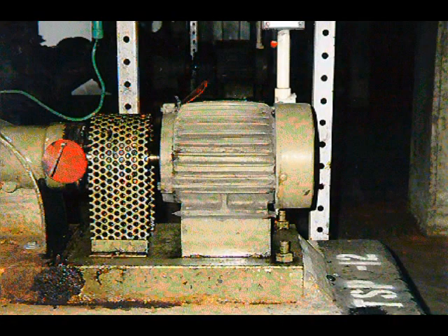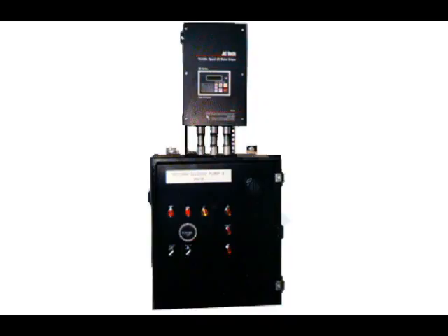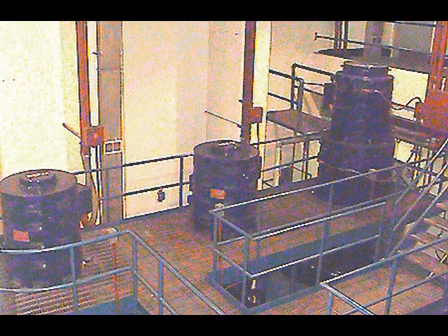There are a number of different types of alternating current motors: synchronous motors or induction motors, which can be either wound rotor or squirrel cage. Synchronous AC motors require complex control equipment as they use a combination of alternating and direct current. Synchronous AC motors are used for large horsepower sizes, usually above 250 horsepower, 186 kilowatt. The most typical pump motors at wastewater treatment plants will be induction AC motors. Induction motors use only alternating current.